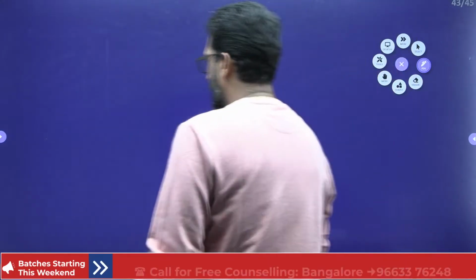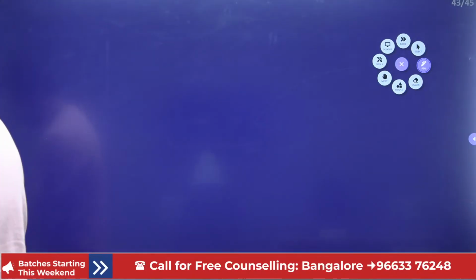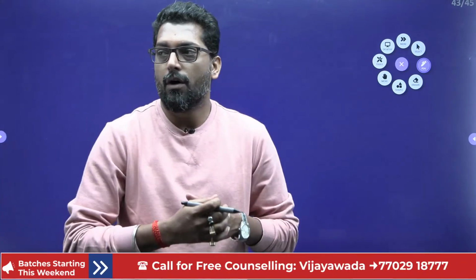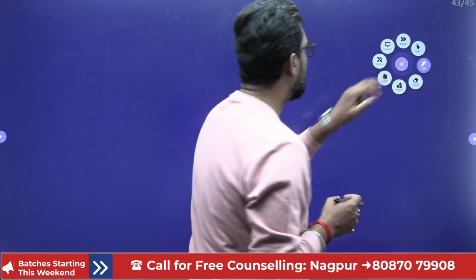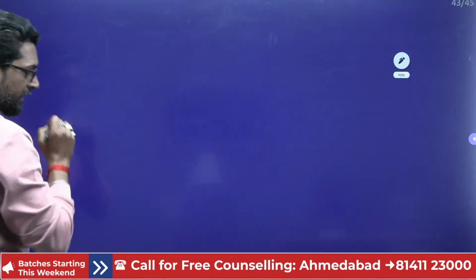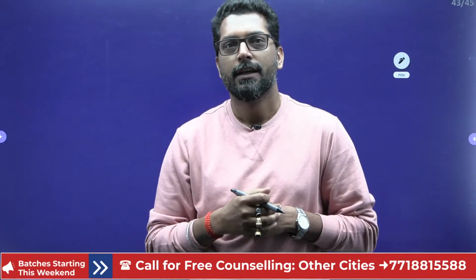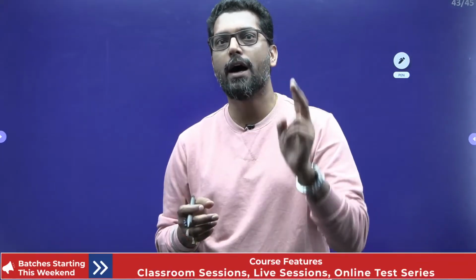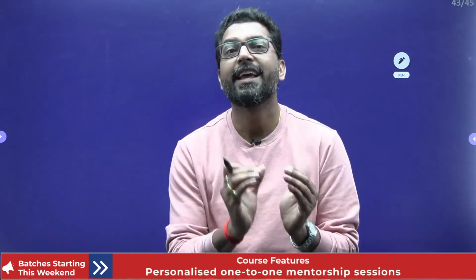We have already seen either an open system or a closed system. This is a very important thing I am telling you. Many students get confused here, that sir, TdS equal to dU plus PdV and TdS equal to dH minus VdP. These are two relations, and these are property relations, and these property relations are valid for any kind of process, and these two relations are also applicable for any type of system.